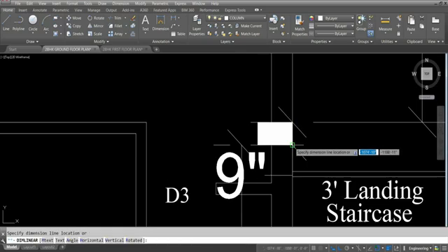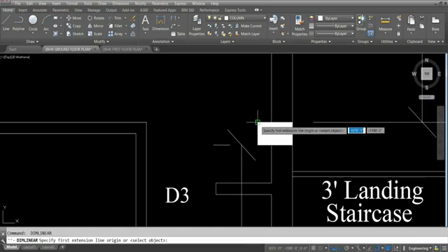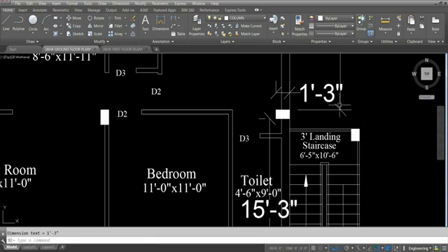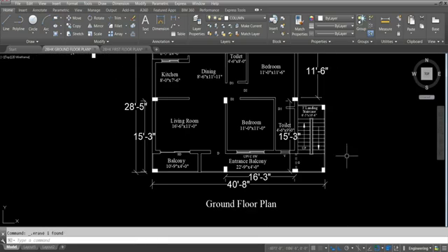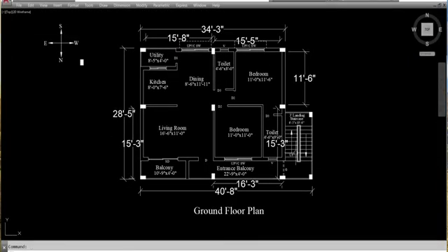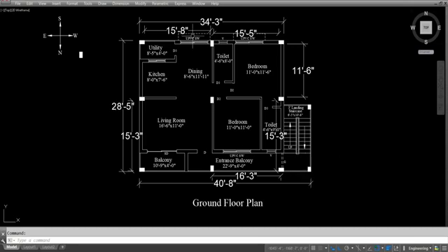Here to here this is 9 inch, 9 inch by 15 inch. This is 15 inch or 1 feet 3 inch. So column to column distance 15 to 16 inch. For G+3 we can take 9 inch by 15 inch, and column to column distance 12 feet to 13 feet